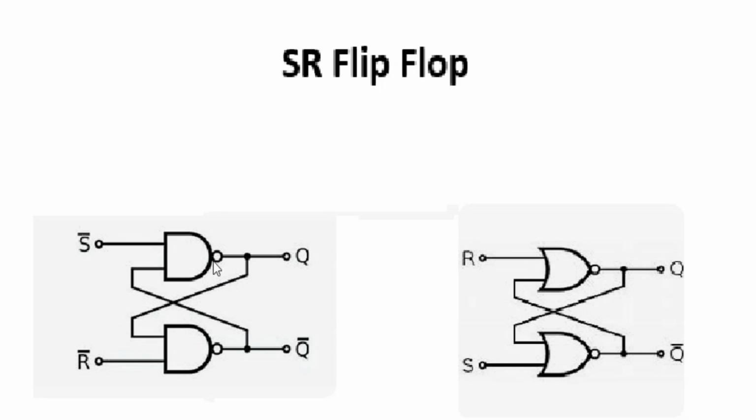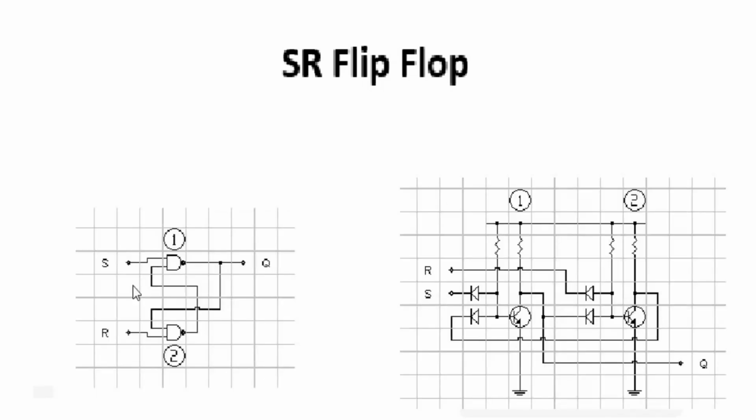It's great that they're NANDs or NORs because that means one less transistor each. NAND gates actually work a bit better, so that's what I'm going to use. But the inputs are active low, whereas for the NOR gate version it's active high. They're actually also flipped. So let's take a look at the circuit. So there is the basic design there for a NAND based.